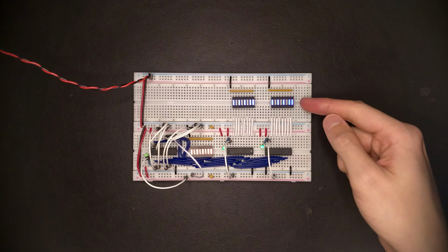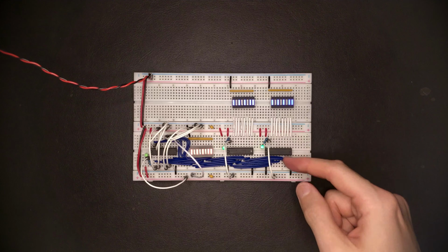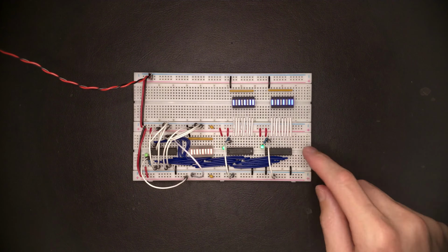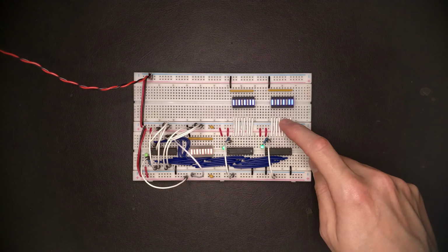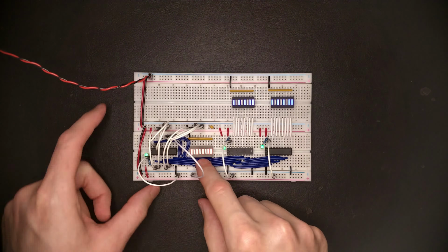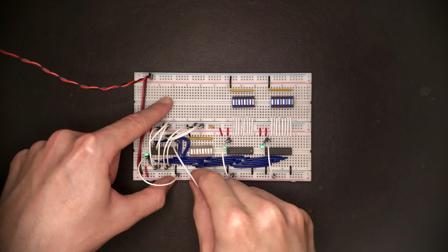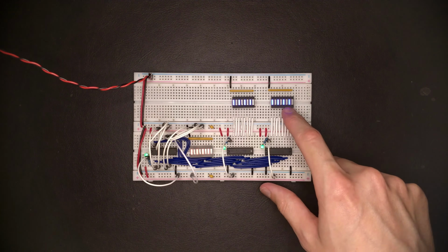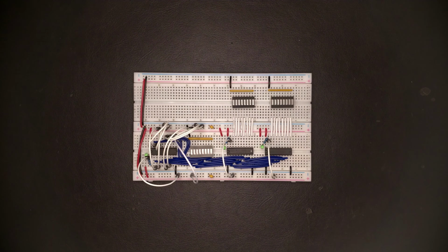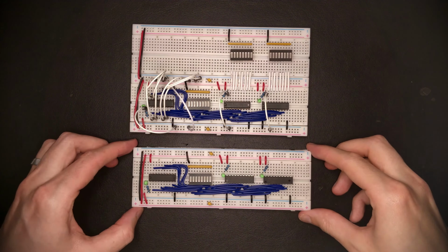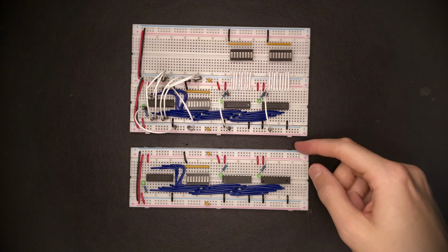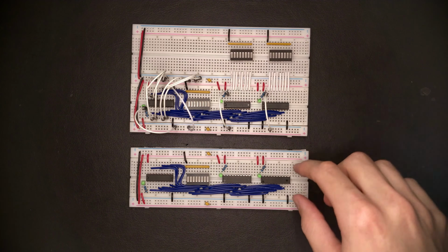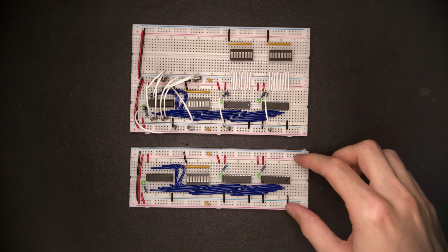We have a second read data bus for which we can enable the driver and actually get the value of the register being produced on that read data bus. And we can also change the value in the register. And as you can see, the new value immediately shows up at the output. Now I've gone ahead and duplicated this register breadboard. Now let me hook the two up, combine the two power rails, and then let's see how we can actually connect the two registers to form one larger register file.